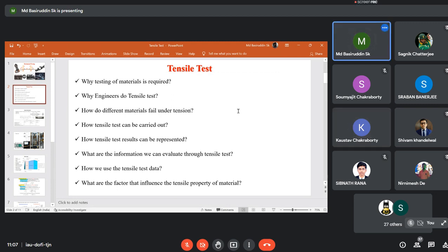Much faster. Though the loading conditions in the impact test are a little bit different, if you go to the micron scale or micro level, you will find that at the crack tip, where the crack generally starts to initiate and propagate, the material is experiencing a tensile kind of force.